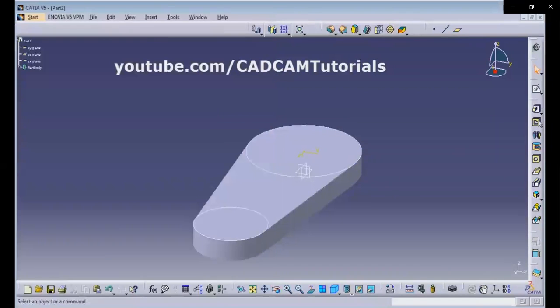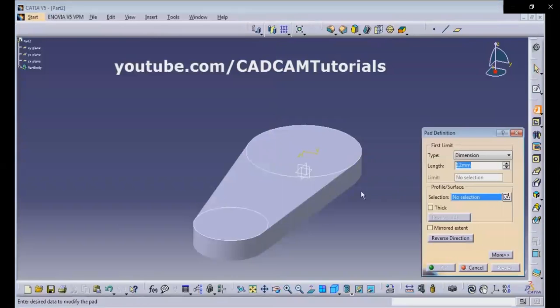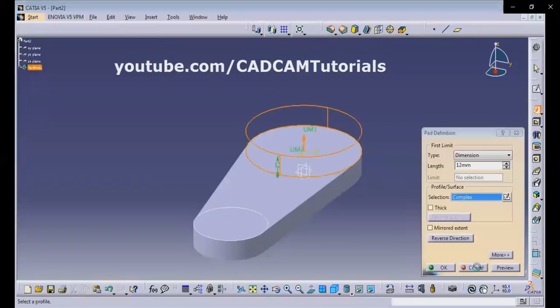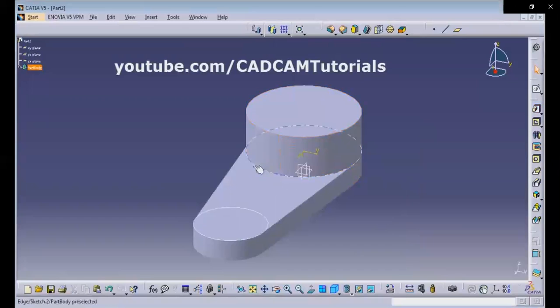So we'll make pad. Now at this time actually these both circles are in the same sketch, but we want to make the pad of this circle only. So on this no selection, right click on no selection and click on go to profile definition, then select this circle. Okay, and give the thickness of 24. Okay, so it will create pad of that circle only.